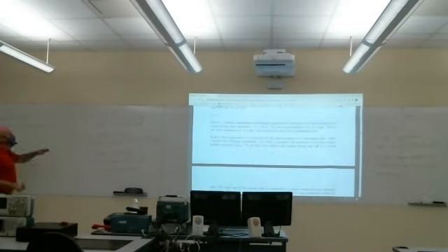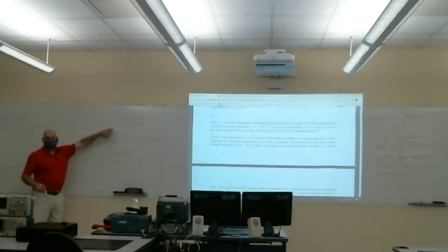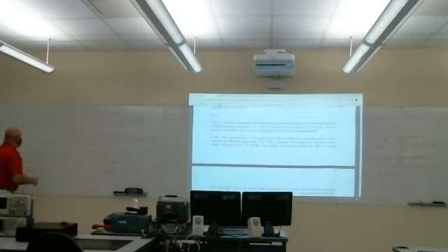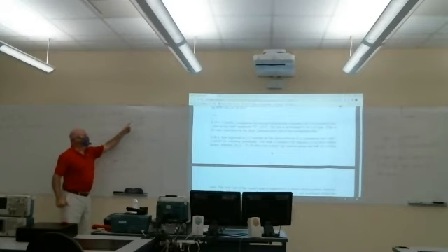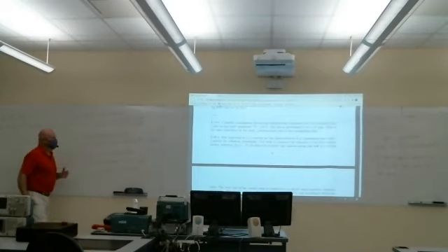So here we have to go to our general equation. This one is the one that we want to use. The first thing we want to do is determine beta L and tangent beta L. This looks nasty at this point, primarily because ZL is this complex thing, but it's not going to be that bad when you plug it into your calculator.